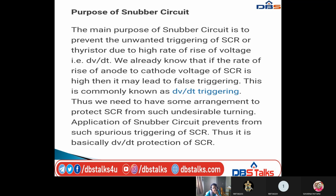The main purpose of the snubber circuit is to prevent the unwanted triggering of the SCR or thyristor due to a high rate of rise of voltage, that is dV by dt. We already know that if the rate of rise of anode to cathode voltage of the SCR is high, then it may lead to false triggering. This is commonly known as dV by dt triggering.